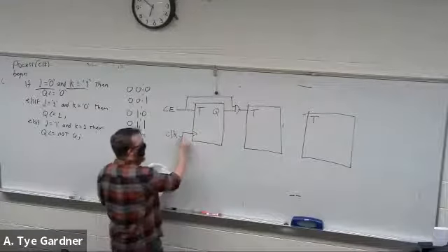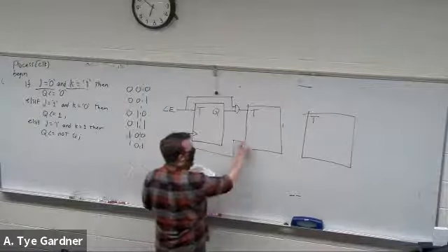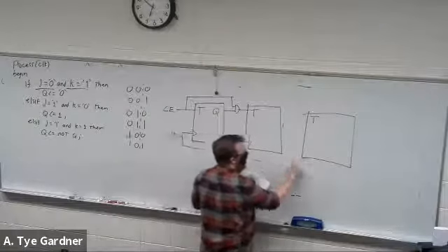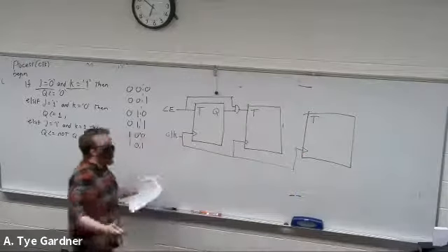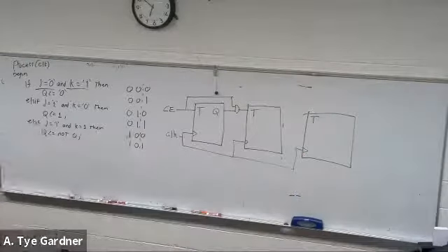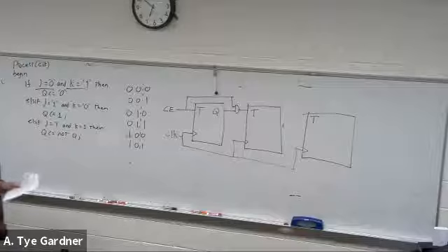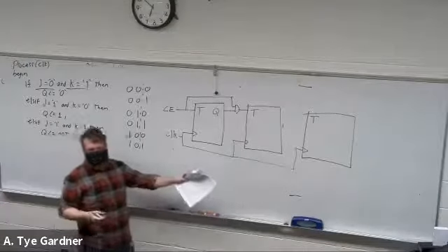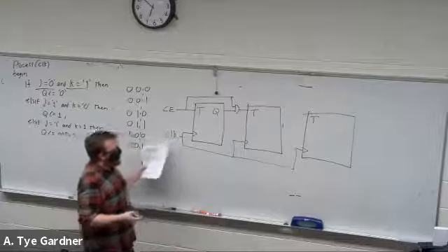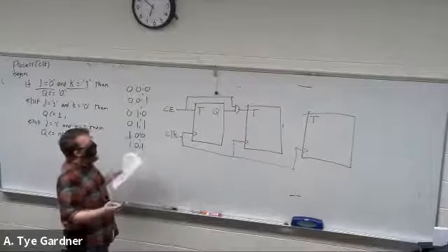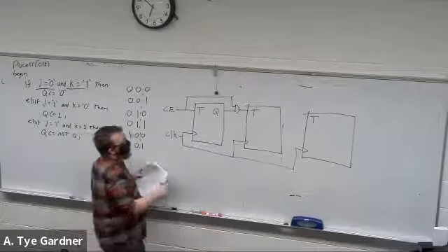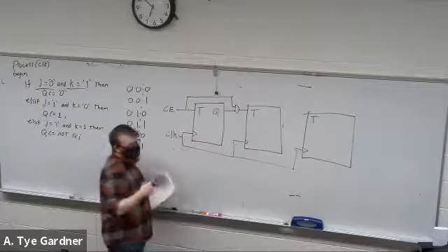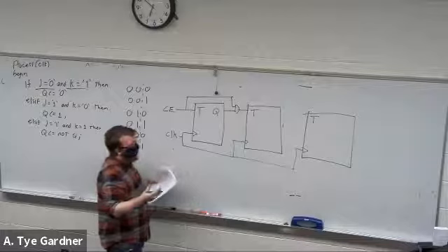Let's feed it around to all of them so that all of them have a clock, so that we're running off of the same clock. So we're nice and reliable rather than having like this weird delay path of clocks. We're just going to run off of the same clock. But we're going to take advantage of this clock enable to toggle or not toggle.